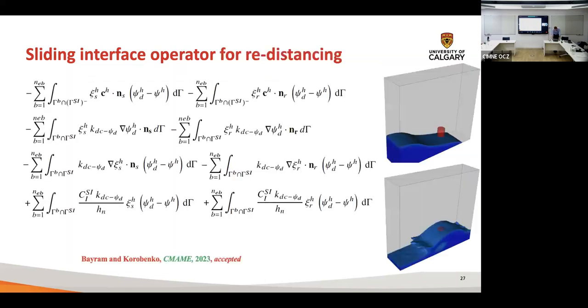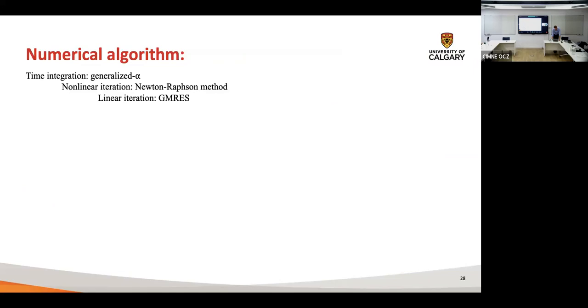Okay. Good. So now the numerical algorithm. For the time integration, we are using the generalized alpha method, which we are now starting to explore. It has its pros and cons, but for the full order model presented here, it works perfectly well. It's second order accurate, implicit, and unconditionally stable. The Newton-Raphson method is used as the nonlinear solver. We derive all of the Jacobian matrices by hand, a good exercise for your students. They're very happy about that.